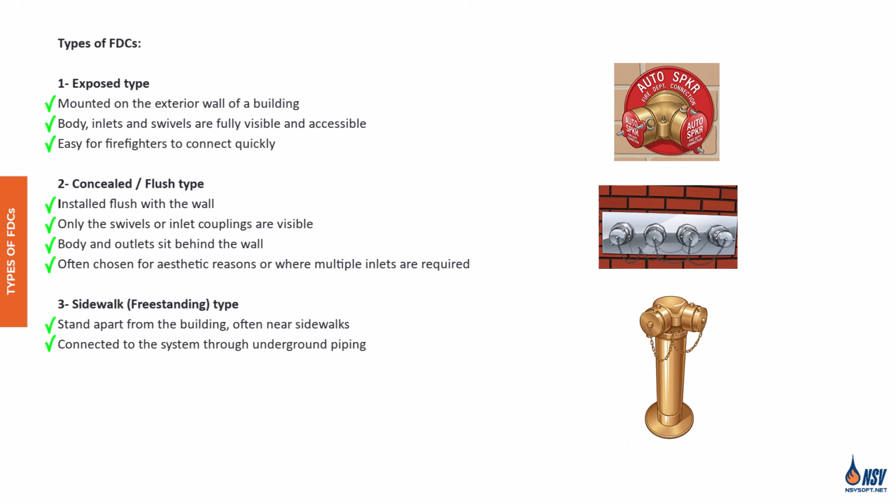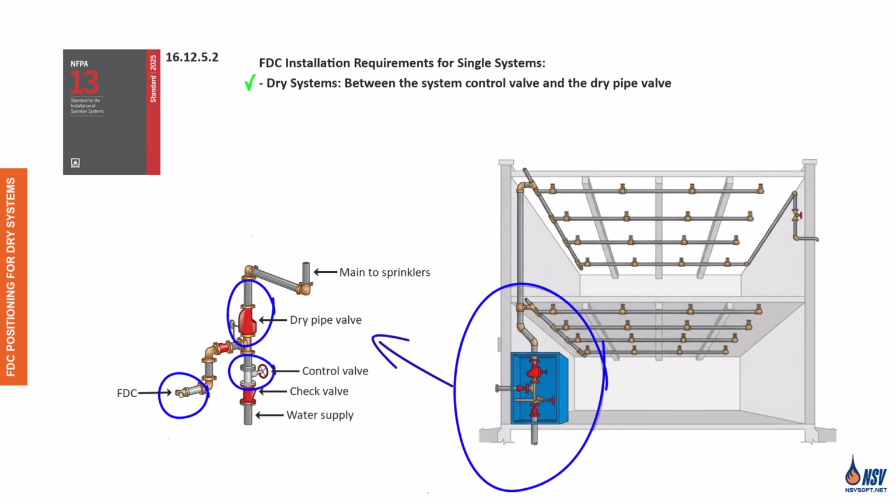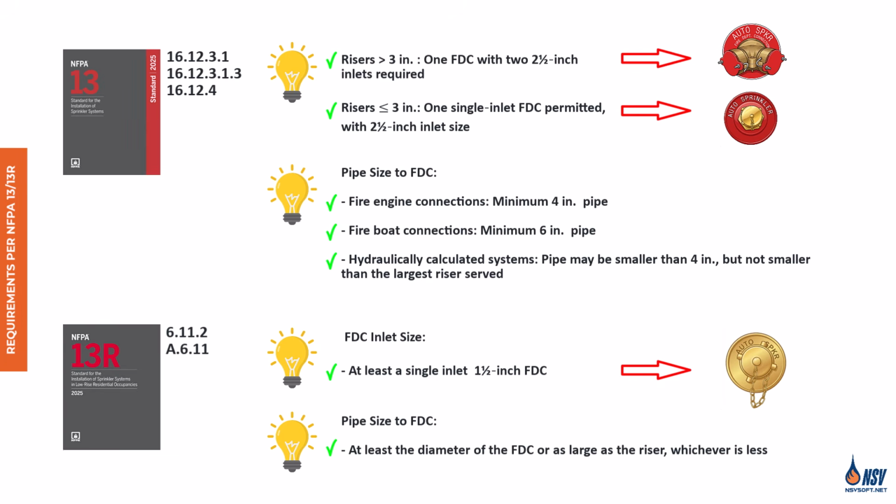We'll cover the number of FDCs required, pipe sizing requirements based on NFPA 13, NFPA 13R, and NFPA 14, the proper placement of check valves, acceptable FDC locations, required clearance, and the signage standards you need to follow.